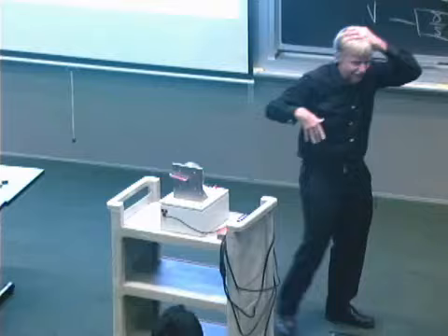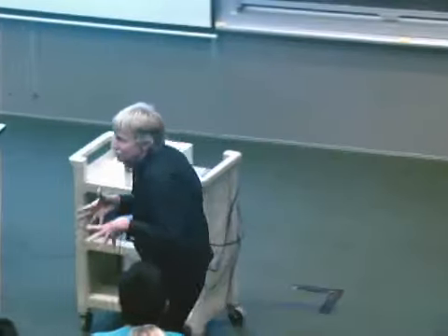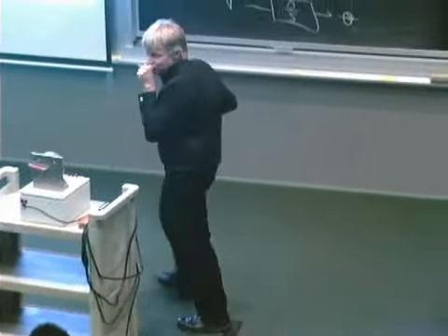Okay, so the $64,000 question. What did I do wrong? The goal was to make a model of the motor, analyze the model, figure out how to put feedback around it, make it perfect. Yes? I made too simple of a model for the motor. I ignored inertia. I ignored all manner of things. I ignored friction. So how can you tell that I ignored those things?